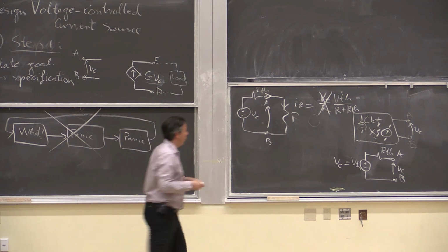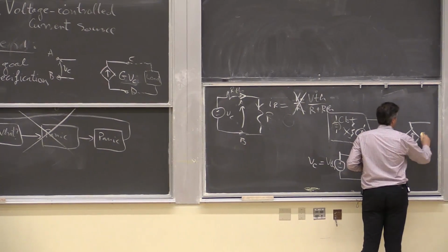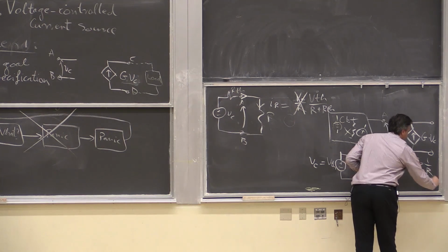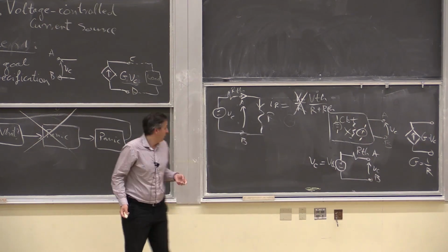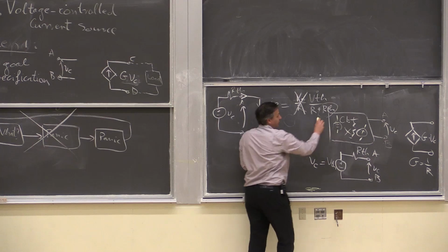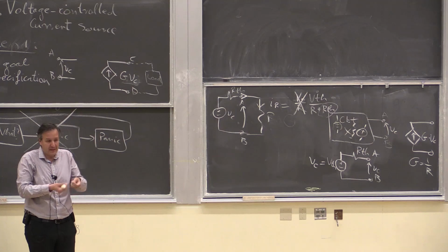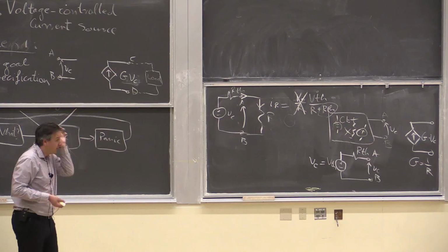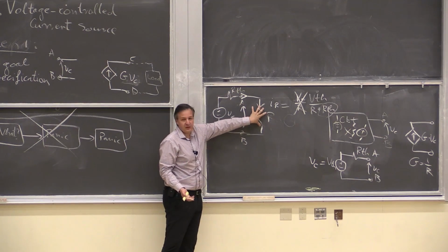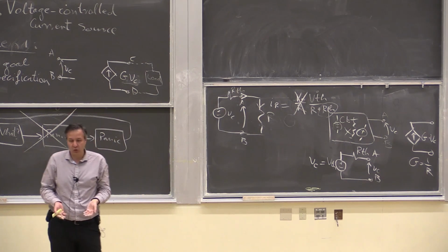Does it make sense? I wanted to create something where the source here is G times VC, where this G equals 1 over R. That's what I want to do. But that's not the case, because the moment I hook this up, there's this R Thevenin term that creeps in. And I don't know what that is. That's some junk in that circuit. So it kind of messes up the value of G. Okay. So this is basically called loading effect, where whatever circuit we add to this circuit X, we're kind of loading it. So we're going to change what that control voltage is.